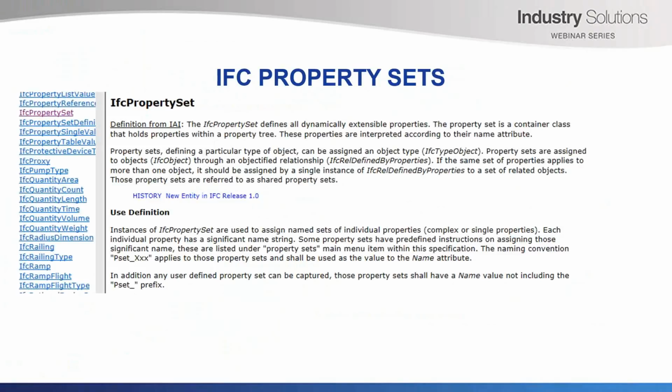But in general, when you talk about property sets, they're just like your attributes. They can be whatever. You can have any names you want and any type of value. So if someone's asking you to give you information, they need to define all that sort of thing for you. They need to tell you what the attributes are going to be called and what their values are and what they actually describe. So that's what property sets are. So basically just think of them like 12D model string attributes, and basically we send our 12D model attributes across to these property sets.